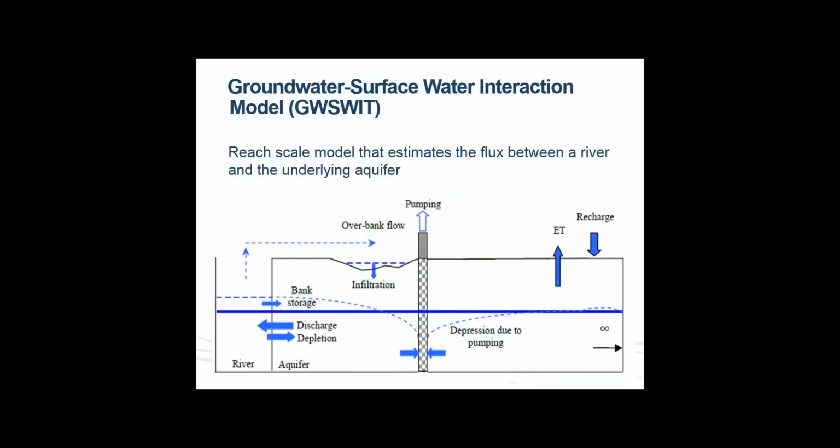However, the model does have some drawbacks, and one of those is that if you have time varying inputs, the model runtime can slow, and this is because each time you change your pumping rate, for example, then the model spawns a new solution to the equations. So obviously if you have a lot of time varying inputs, the model then slows down. The second issue is that in its current form it doesn't display groundwater heads, and if you want to be able to calibrate your model to observed heads, obviously that's a concern.